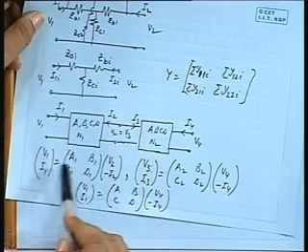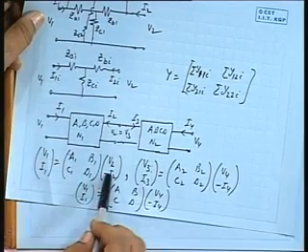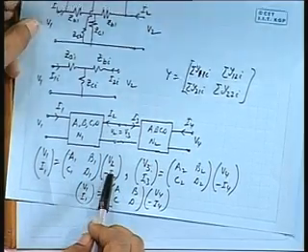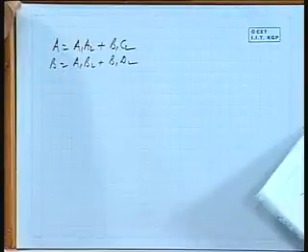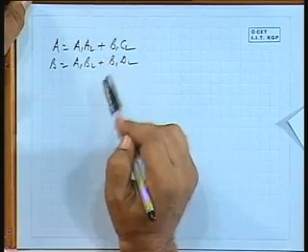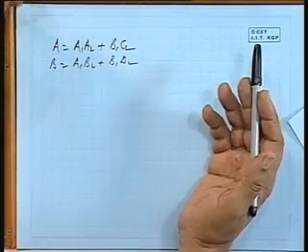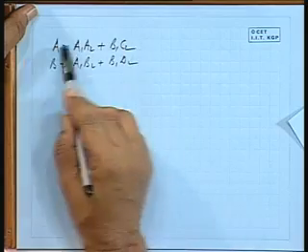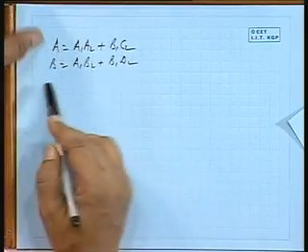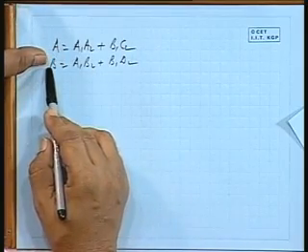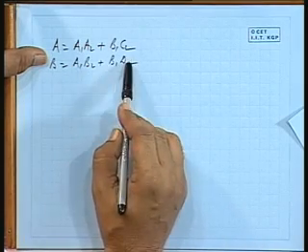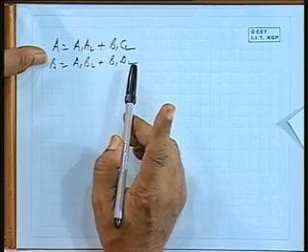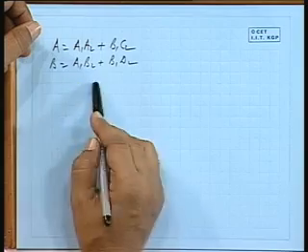B is the ratio between voltage and current, that is impedance, and C is current over voltage, that is admittance. So the B and C product will also be dimensionless, one is mho, the other is ohm. So this conforms to the dimension of A. Similarly, B is impedance multiplied by a constant, because D does not have any dimension, it is the ratio of two currents. Similarly C and D you can write.